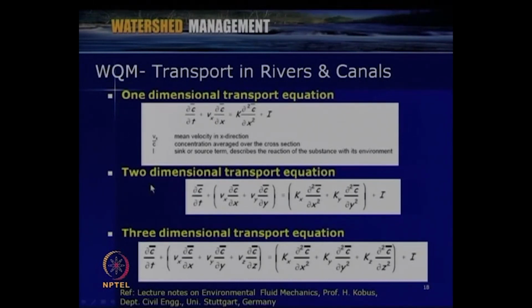Similarly, if we are considering two dimensional transport water quality modeling, we have to solve the equation in x and y. This will be the governing equation, and then the three dimensional transport equation will be with respect to V x, V y, V z, and we have to solve this system coupled with the flow equations or continuity equation and the momentum equations.